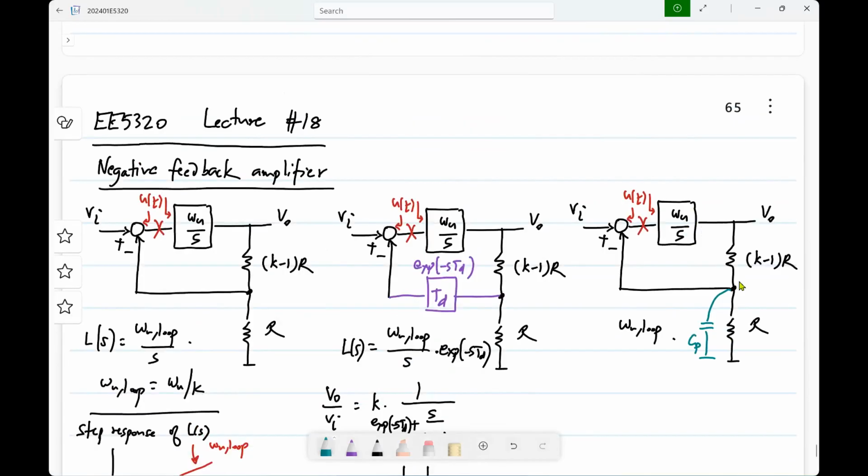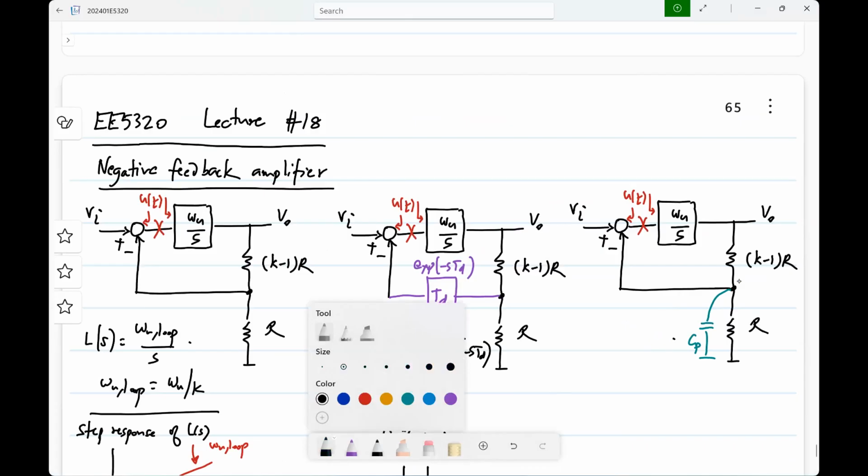So in any first order case, how do you find the pole? You find the effective resistance. Eventually you can reduce the circuit to having only one capacitor or one inductor. Then you have to look at the effective resistance across the capacitor or the inductor, and from that you can find the pole. These things you should be able to do intuitively. From your old course, electrical circuits and networks, there is an assignment on first order circuits, with time domain and frequency domain responses. You can go through that. Try to get the answer without deriving it, and then derive it and make sure that you get the same answer. That's how you build intuition.